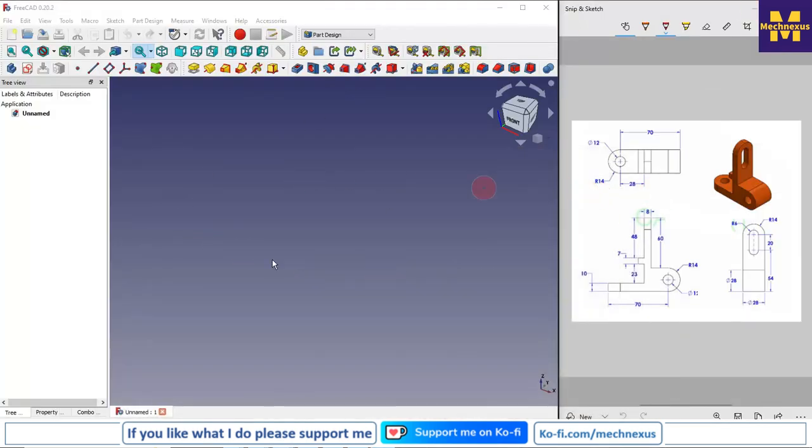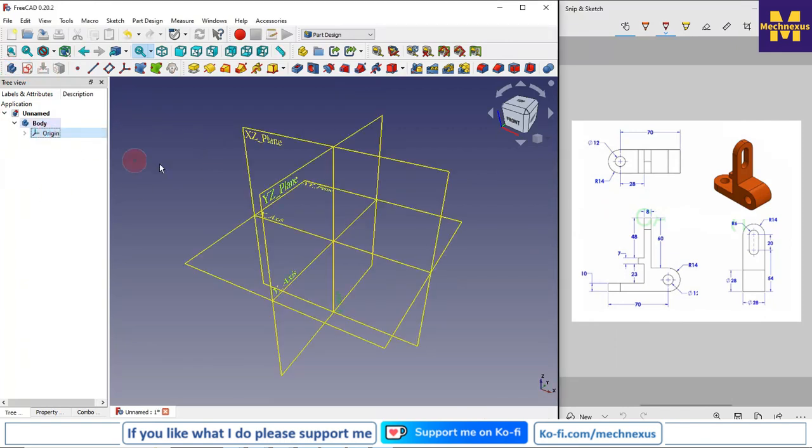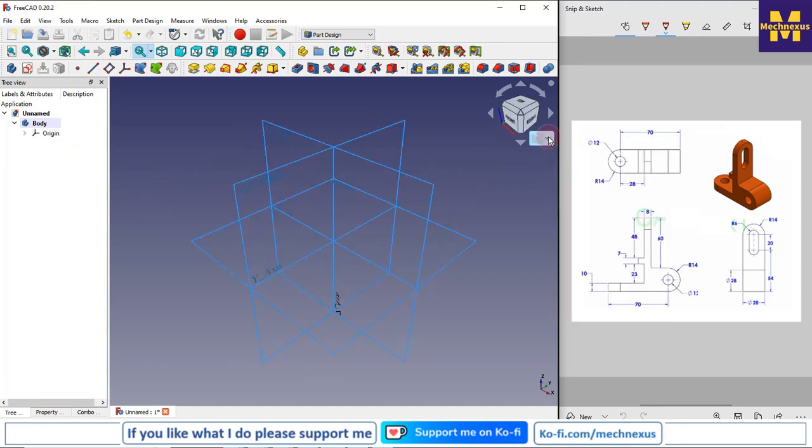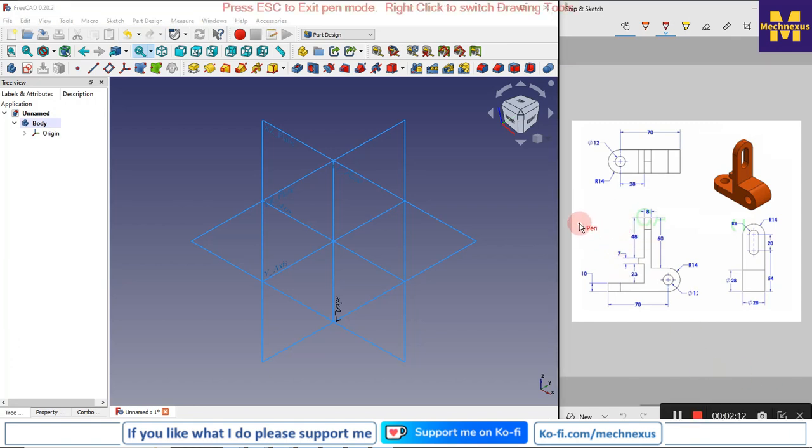For this I will create a body, then I will press the space bar to turn on my plane, and here I will switch to the orthographic view. Now, this is a very simple part, and this tutorial is designed for the beginner user. We will create this profile first, then extrude it, and then add this slot and hole.